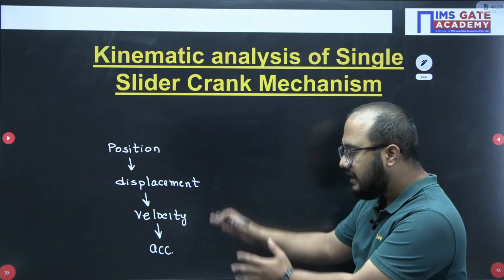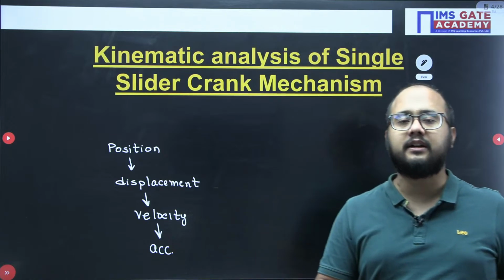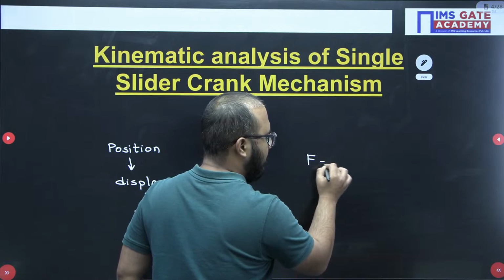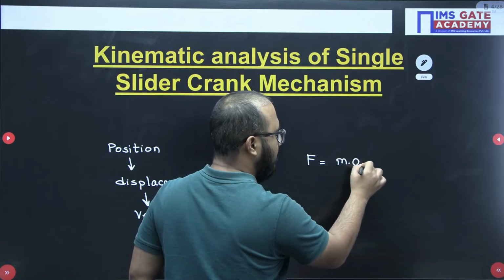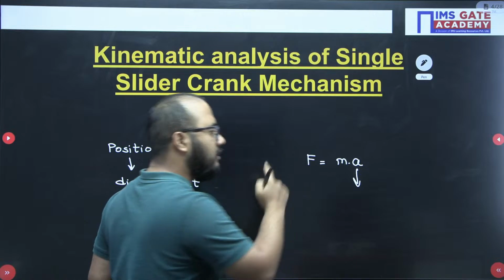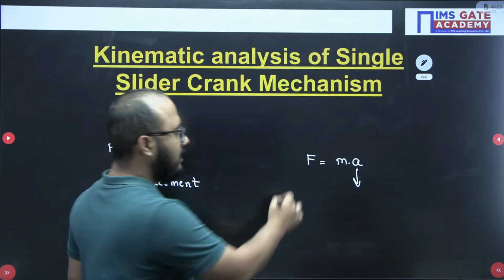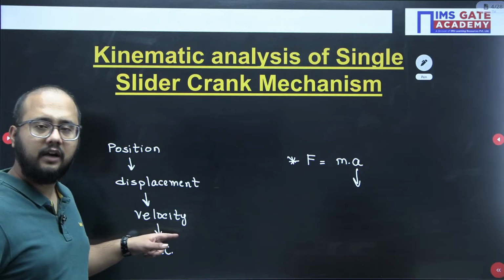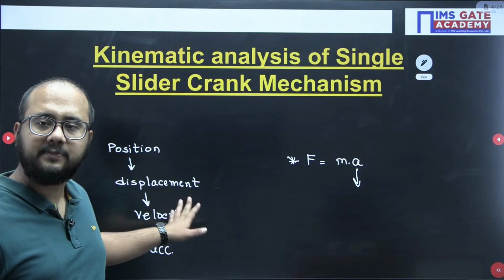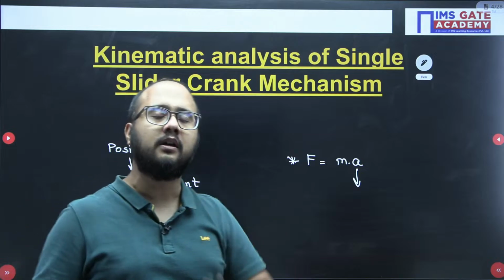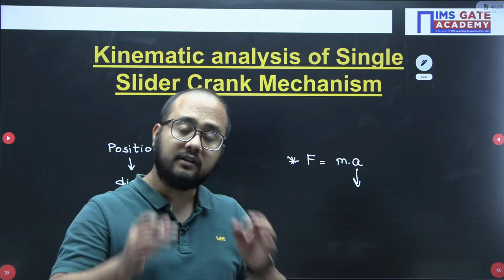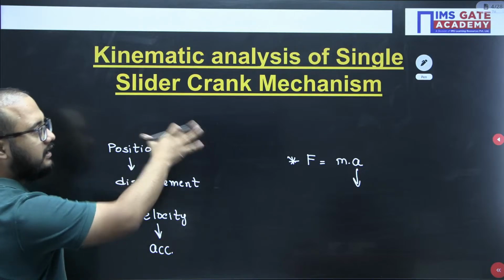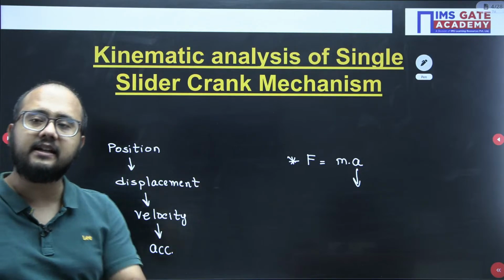Once it is done, then we can go for dynamic analysis. As I told you, force from Newton's second law equals mass into acceleration. So without acceleration, you cannot calculate the force, right? So in order to calculate acceleration, we need to know about velocity. And for velocity, we need to know about displacement. And for displacement, position has to be clear. Okay, so that is the sequence of discussions that we'll be having in kinematic analysis of single slider crank